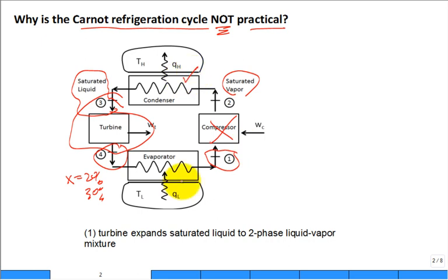These heat exchangers, no problem. Okay. Now, you might say, isn't this heat exchanger kind of magical because the fluid inside the tubes and the temperature that you're driving the heat to is the same? Yeah, I know. When you take heat transfer, to motivate the heat transfer, I need a delta T and an area, blah, blah, blah. But in the limit, these two temperatures are the same. It just means I need an infinitely large heat exchanger. In practice, people focus on improving efficiency in this area. But the reason it's not practical is not so much the heat exchanger, the evaporator and the condenser. It's that the turbine doesn't exist, and we have an unhappy compressor.